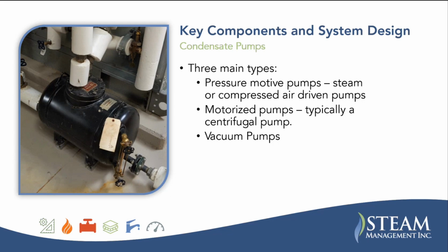There's some advantages for using these. They can get air out of the system quickly. They can get steam from the boiler to the furthest radiators quickly or easier. They solve a lot of steam distribution problems, and they also enable smaller pipes to be used because there is more of a vacuum on the system. So it's easier to get the steam out to the ends of the system, even in a smaller pipe, I guess. Where needed, they can also lift condensate from low points in the system. So that's just something to note there.